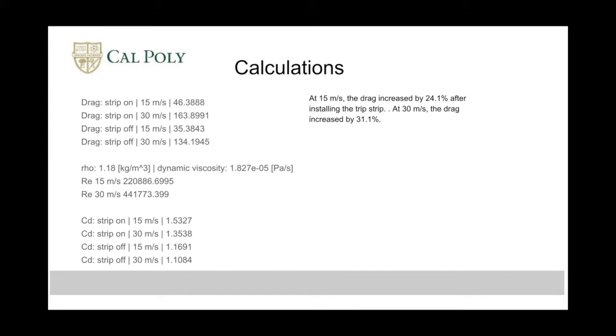We calculated drag using midpoint Riemann sum summation of the integral that calculates drag. We used the midpoint as opposed to the left or right because this gives us the best estimation of drag at each point. Using the left or right angle would result in asymmetrical drag along the top and bottom.